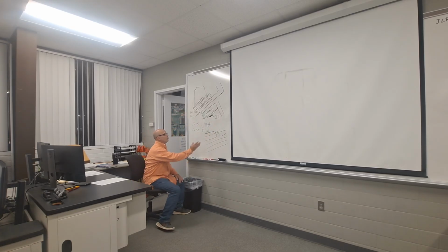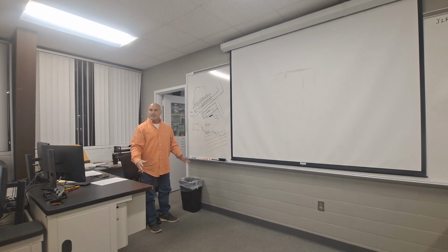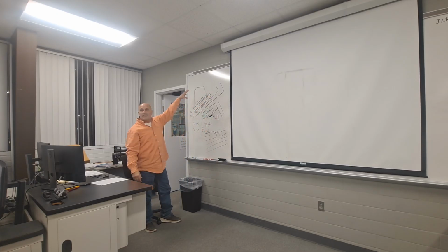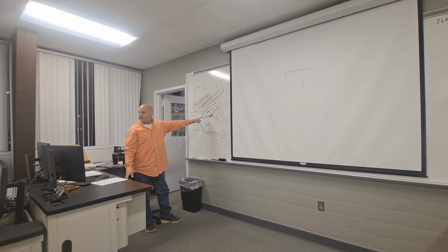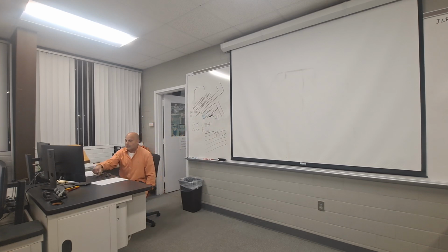If you get up into your parking lot, and I've had students, you don't have to have just one parking lot. I have students that have a parking lot, they have some more back here, they have some over here, maybe by the field house for the coaches to park and stuff. A minimum of 100 standard parking spaces, a minimum of 8 handicap parking spaces. Now your handicap parking spaces always need to be nearest the facilities, of course. Okay, so you're gonna have those 5-foot wide sidewalks. There should be a sidewalk right there by your handicap spaces and nearest the facilities as you can.